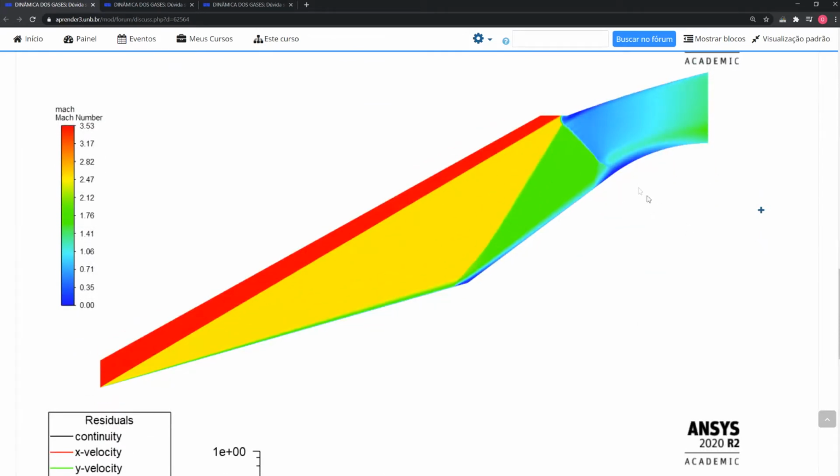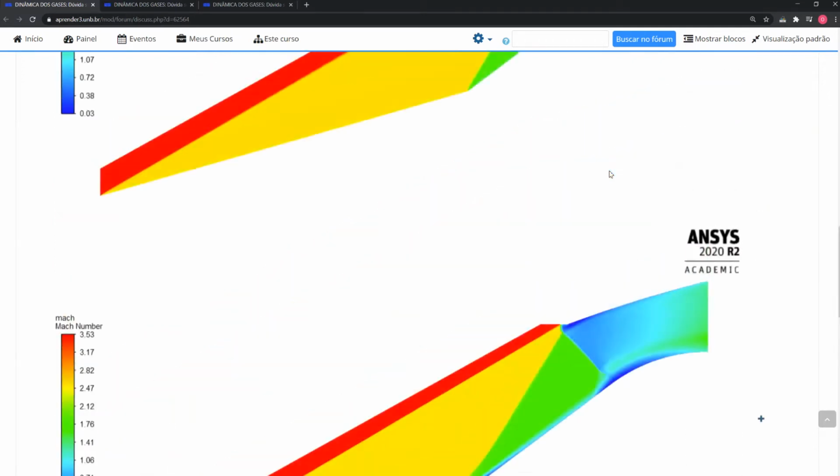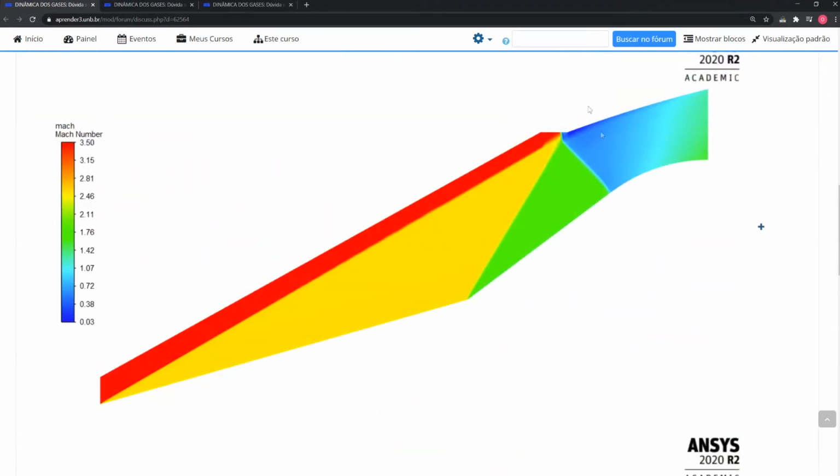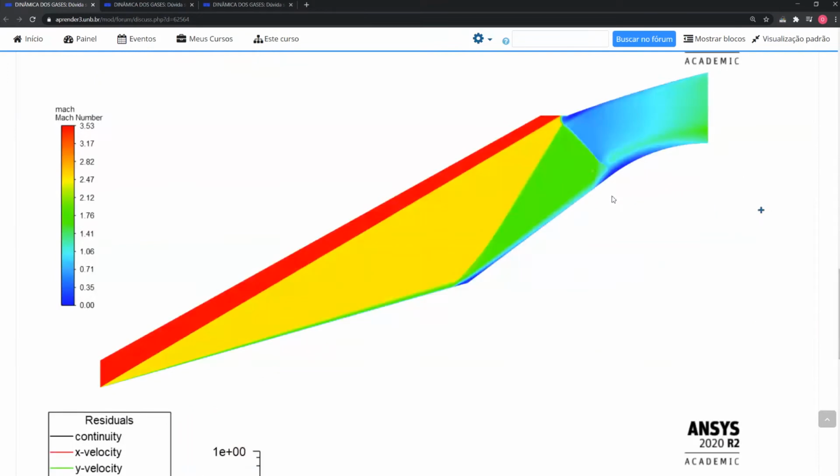Also, what can happen in this case is that your flow has a vortex, right? And the flow is more constrained, so the efficient flow passage here is smaller than you had for inviscid simulation. So flow must have higher values of pressure, for example, density, and probably will have a bit higher values of temperature.